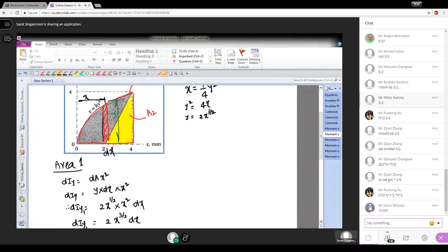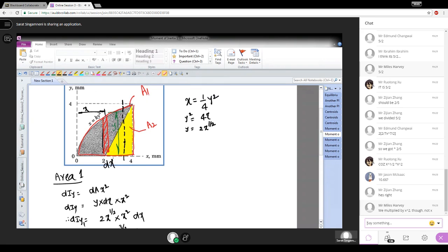But now we need to subtract the moment of inertia of that triangle about the y-axis. So how do we get that? So we need to use the parallel axis theorem. For example, the moment of inertia of the triangle, this triangle, about an axis passing through the centroid and parallel to the base, this base, we can calculate this. I will pull out from the formula sheet. If you have the formula sheet, you refer to it. It's too clumsy for me to move to different screens with all this setup, so I'm not doing that.